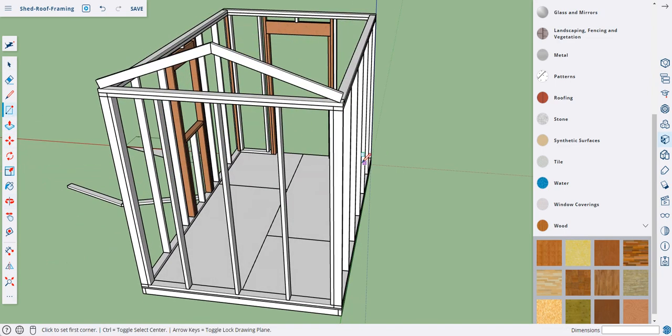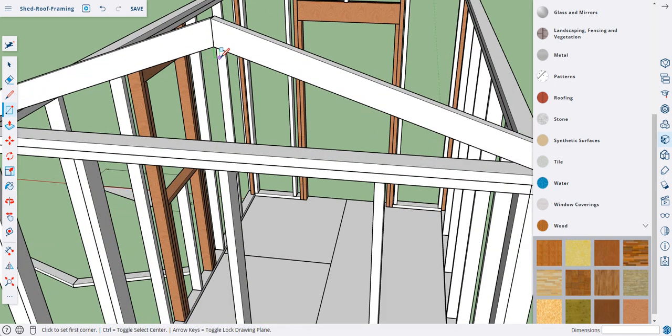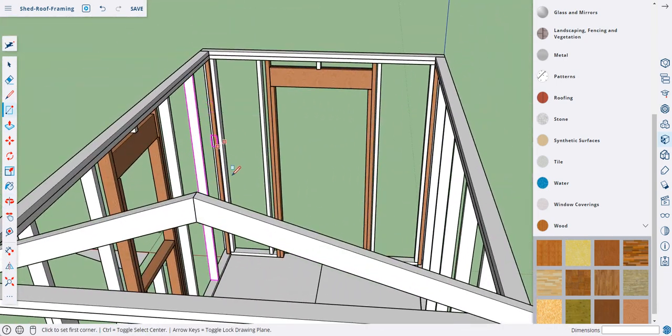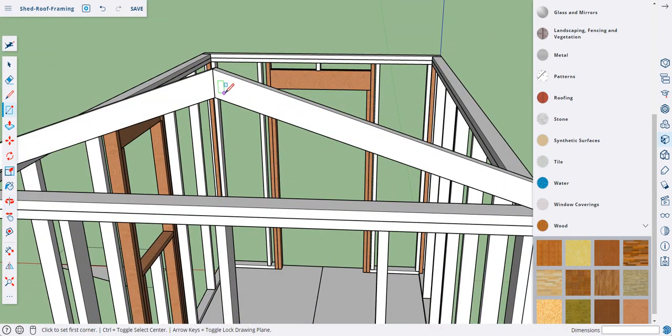Okay, and we can do a rectangle standing up. We just have to do it on a face that's already standing up, like this one. So let's click here and drag it, and on the green, make sure it's on the face, and then type in 1.5, comma 3.5. Okay, and we're going to extrude that,